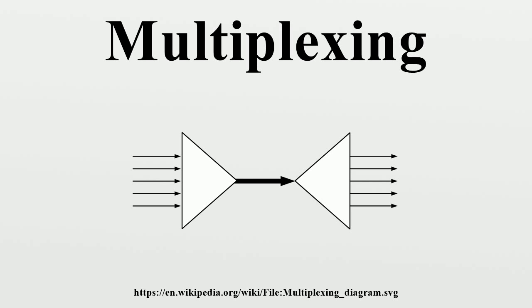Analog broadcasting: in FM broadcasting and other analog radio media, multiplexing is a term commonly given to the process of adding subcarriers to the audio signal before it enters the transmitter, where modulation occurs. Input signals at an ultrasonic rate, and then filtering out the higher harmonics. Multiplexing in this sense is sometimes known as MPX, which in turn is also an old term for stereophonic FM, seen on stereo systems since the 1960s.